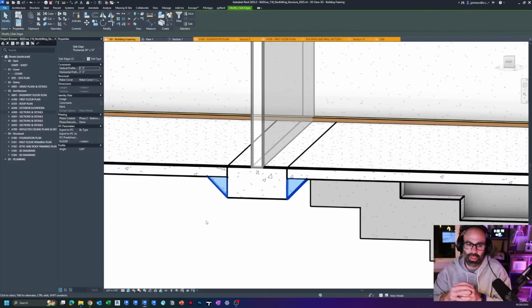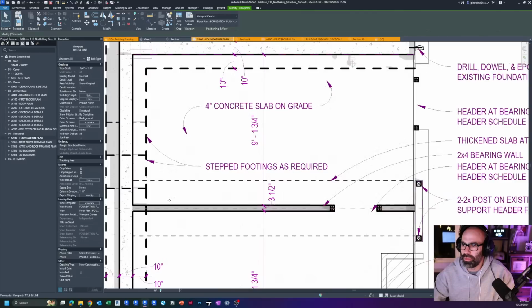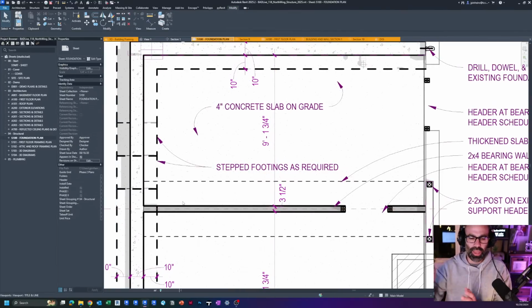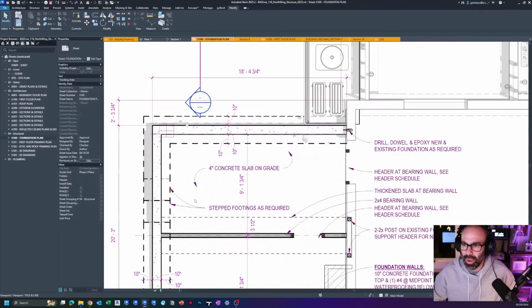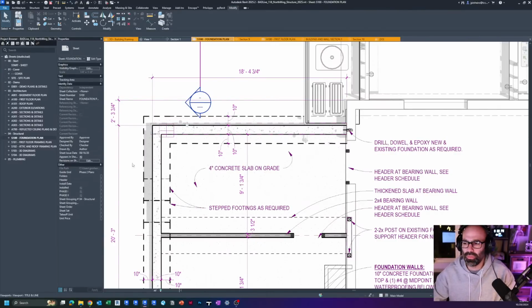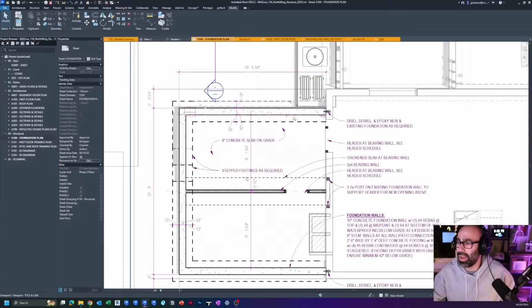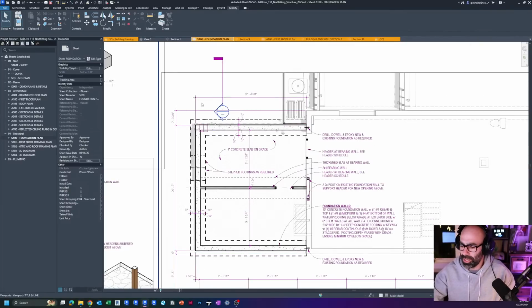I like this one because graphically it showed really nice in the structural foundation plans, because you just have that line that you could use. Let me get out of here. So you can see that line that you could use from the 2 slab edges that represent that haunch slab. But that's really completely up to what you guys want to do. There are plenty of ways to approach that. I think I could also have used some form of a footing family and maybe even attach it to the bearing wall, which may not be that bad of an idea. Modify some form of a strip footing family. So hey, if anyone else has any ideas on how they approach this, I'd love to hear it. But that's how I approached it for this particular project.